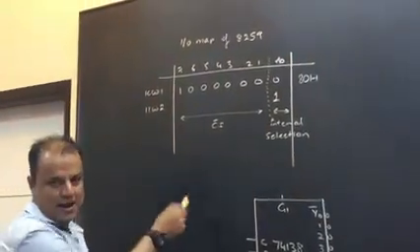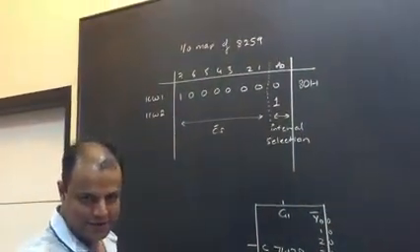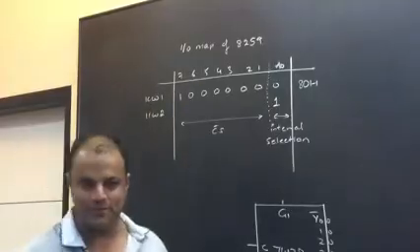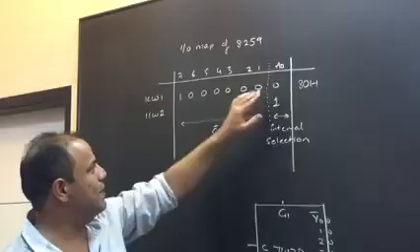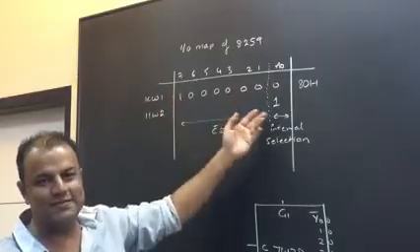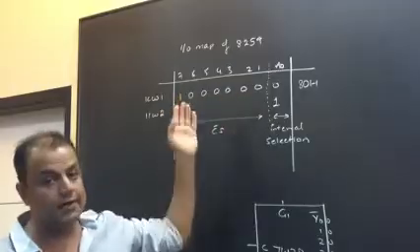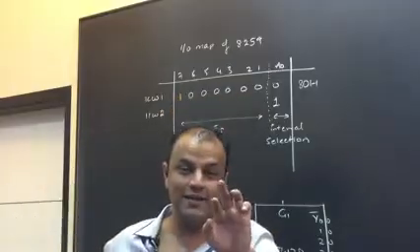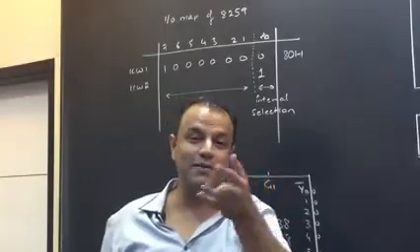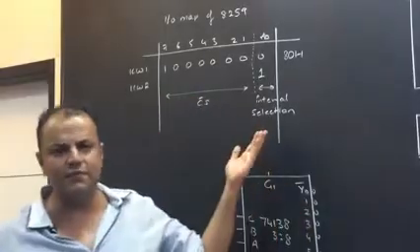So we start our designing part. Okay, pay attention over here. The first thing you need to make is an IO map. Okay, very simple. IO map A0 to A7, that's your address bus. Because we're doing IO designing, addresses are 8 bits. You can even take A8 to A15. If you know timing diagrams, the address gets duplicated on the lower bus and the higher bus because the address is only 8 bit and the bus is 16 bits. So you can even take A15 to A8.